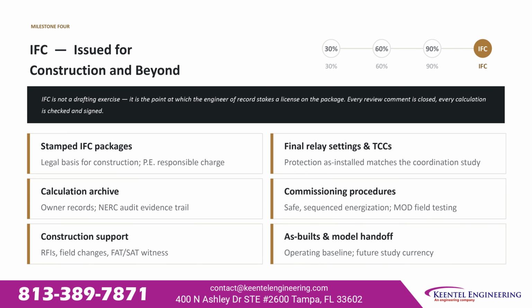The stamped IFC package is the legal basis for construction. Final relay settings and time current coordination sets are issued. Protection as installed matches the coordination study. The calculation archive is the owner's record and the NERC audit evidence trail.